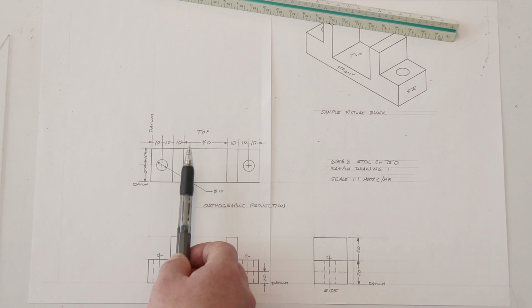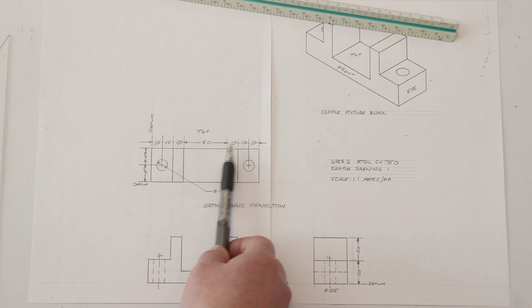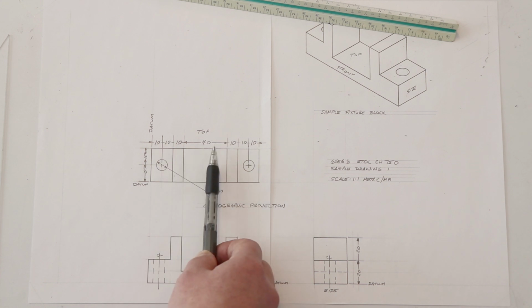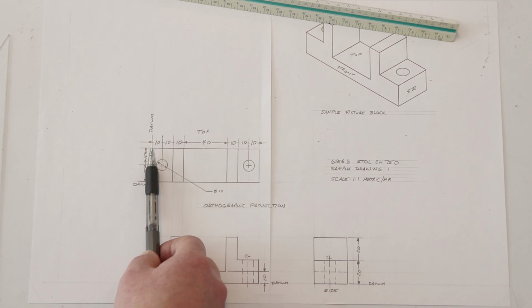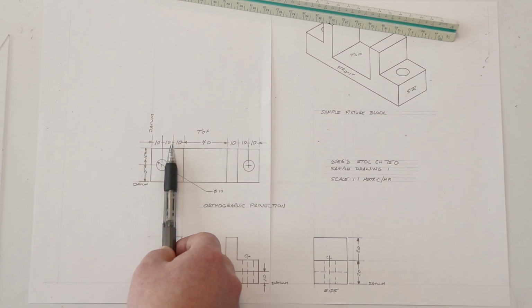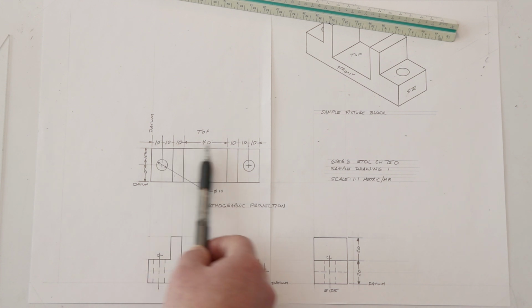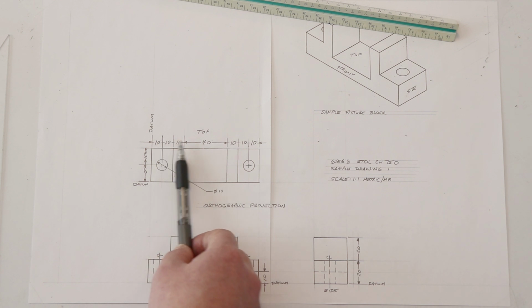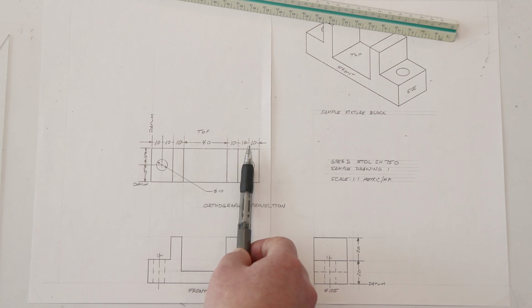Now the problem comes in later when I'll show you when we're laying out parts and when we're talking about measurements. The problem comes in being accurate when you're laying out cumulative measurements like this. You either have to do some math or you have to be extremely careful with how you measure cumulative measurements off of one measurement. So let's say we laid out the scale here and measured 10 millimeters, and then we moved our scale over and measured another 10 millimeters. And I'll get into more details on these measurements, but you have to be careful when you start using datum lines for reference points in a cumulative fashion, because there's going to be an extra margin of error because of the manual placement of your scale on the sheet metal.